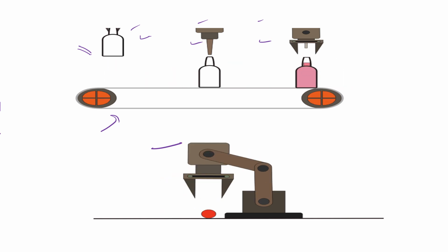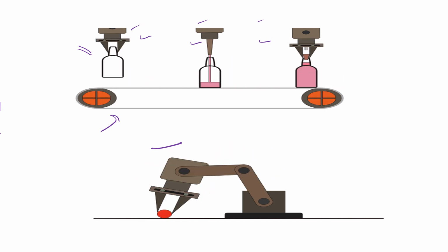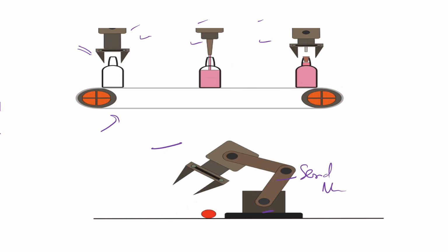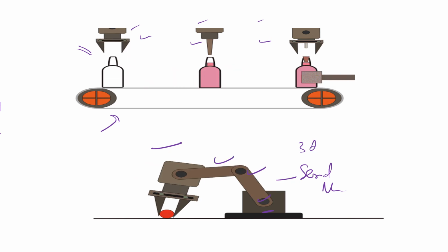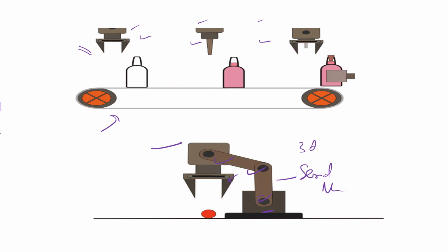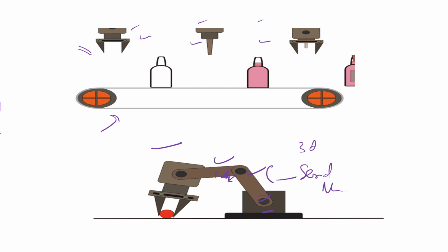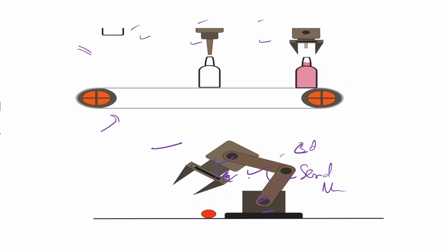So these are all servo motors, and here they are also used to pick and place. Here the end effector is a gripper. This is one serial manipulator. Why is it a serial manipulator? Because one end is fixed, the other end is free, and since it is a serial manipulator, the number of joints equals the number of degrees of freedom. So one joint, two joints, and three joints. The degree of freedom for this manipulator is 3 DOF. Then you can use the end effector, and you can see the length. Here is also one more joint. This is rotation, this is rotation. This is a revolute joint, and this is also a revolute joint. And see here it extends, so here you have a prismatic joint. So I can say totally 4 degrees of freedom: one, two, three, and then prismatic.